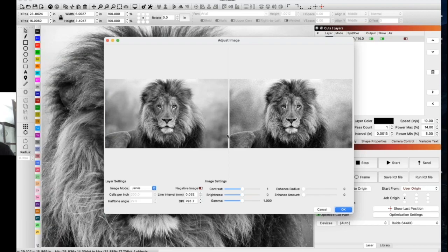Yeah, anything that you can do. I have swatches of test material in my shop, and I can see exactly what they're capable of. We know what the machine can do, but what's the limitation of the material? If we are working with paint, it's not going to take much to eliminate all those dots around it. With acrylic, at what point are we blowing away all of those surrounding areas of the plastic? So running some type of test pattern on these materials to know what the machine is capable of and what the material is capable of is highly beneficial.